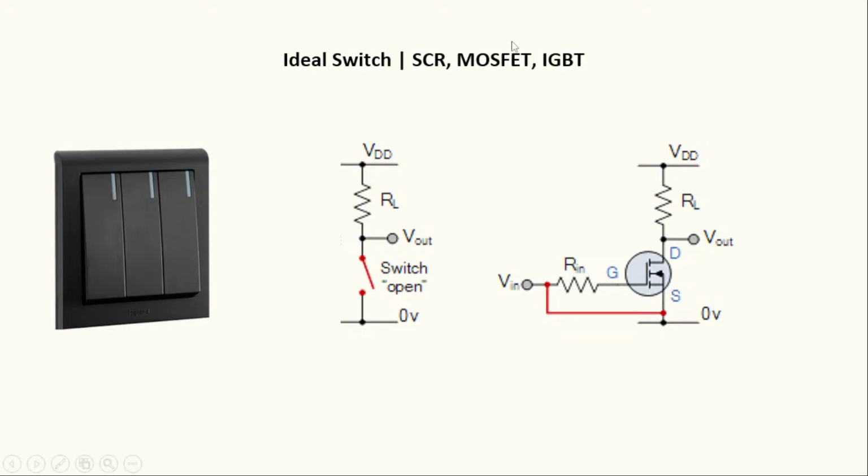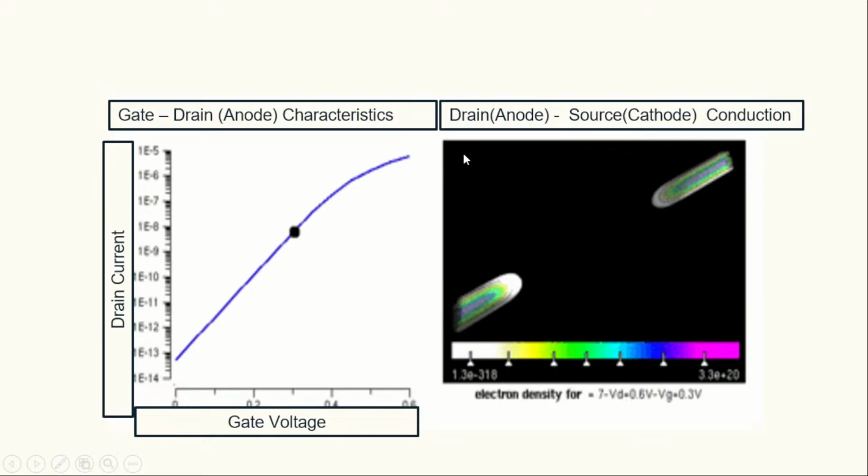Coming to those switches, MOSFET and IGBT. For example, in our control circuit or conversion circuit, we have a MOSFET switch. We know MOSFET has a 3 pin configuration: drain, gate and source. The drain acts as the input, and the source acts as the output. The gate needs a pulse, right? Whenever we apply the pulse, automatically it will turn on, like when we turn on the switch or ideal switch, and automatically the output device will work.